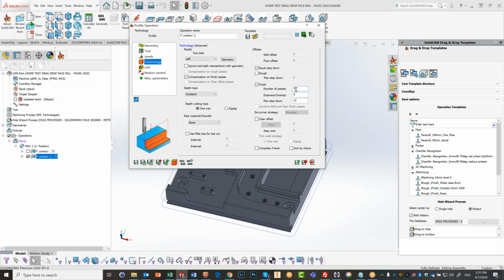Exactly. This is what I'm asking, because I thought that I needed to do 2 now. Very good. The reason this does what it does is actually like this. You probably all notice as well that let's say you have a tool that's pretty long, and the wall is also a pretty long wall. If I were to take it all down in 1 pass, most likely your wall will not be exactly straight, because there may be some deflection because of the tool. If I'm wrong, correct me, but that's usually what will happen.